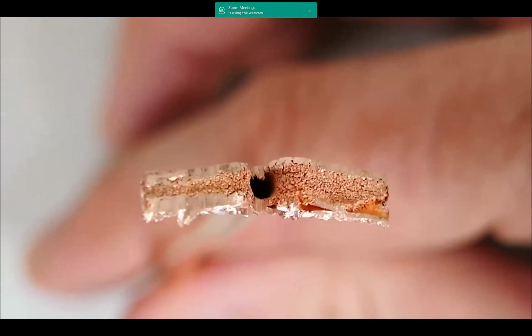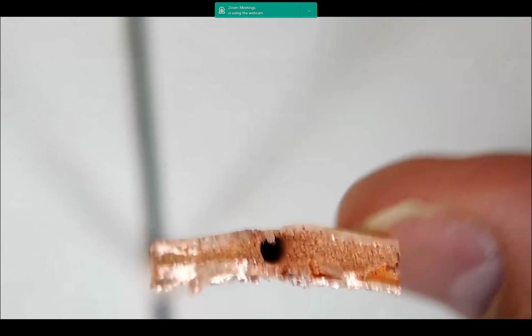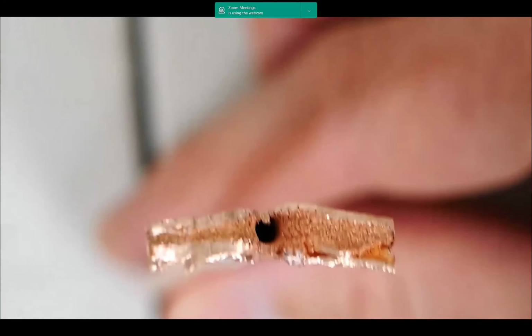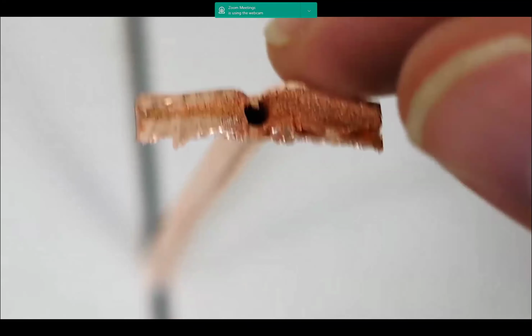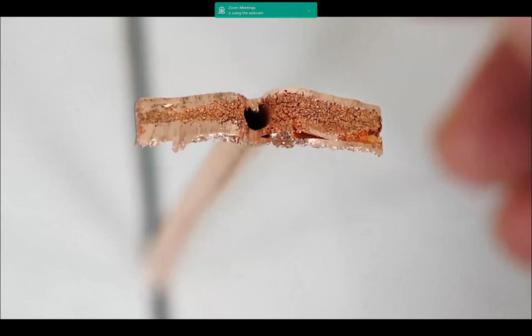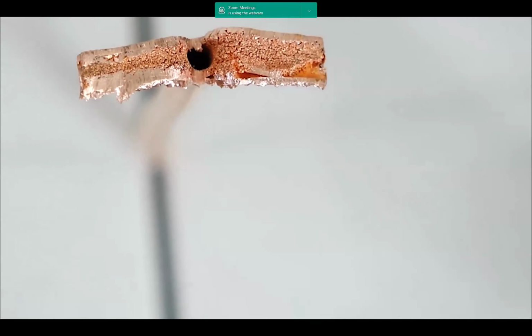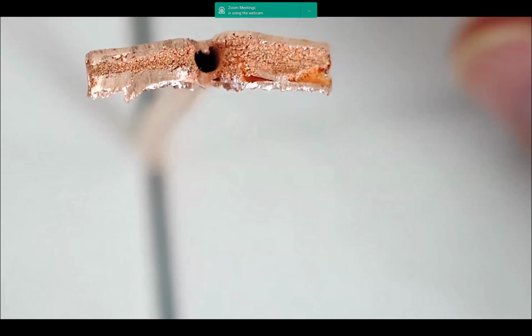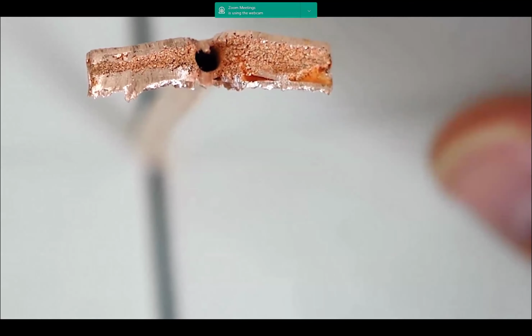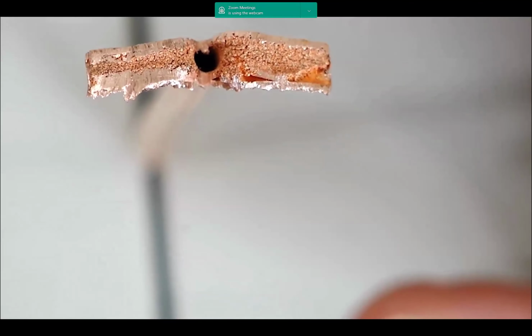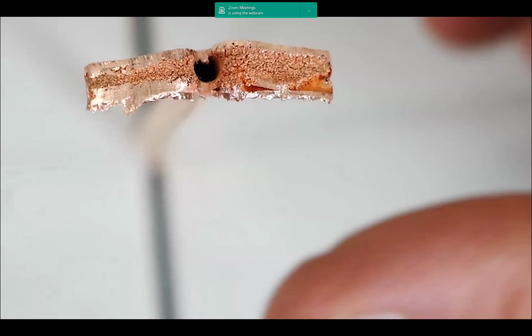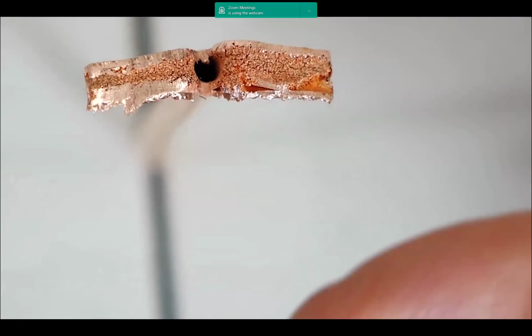Usually what they'll do is they'll get a regular copper pipe and fill it with a little bit of water, and then they'll let that water boil, and then they'll seal off both ends of the pipe. So that all that's left in there once it's sealed off and cools down is a tiny little bit of pure water in a vacuum. And so there's a really low pressure in there, because the water that was hot vapor condenses down once it cools down, but the ends are sealed.